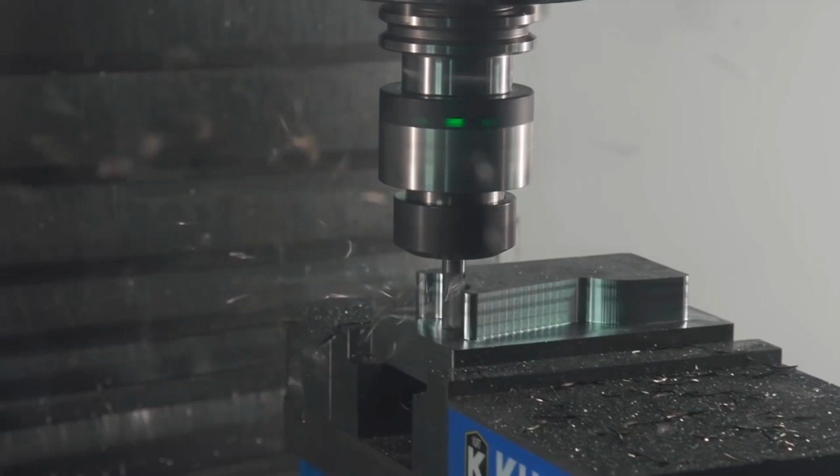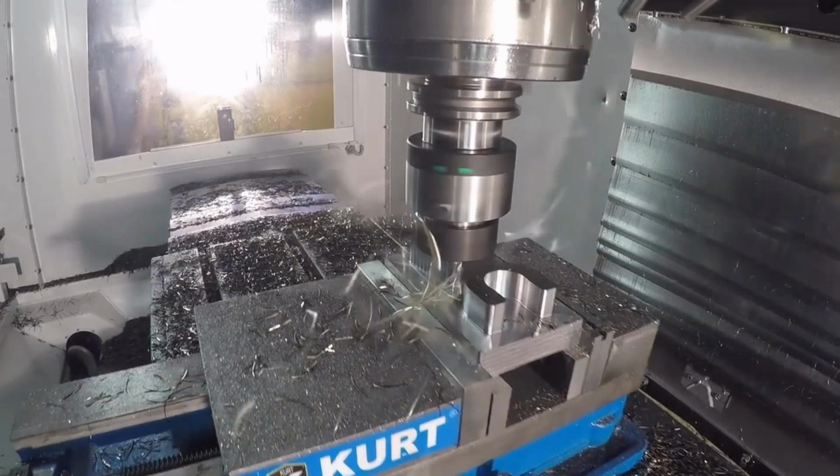If we look at some of the full 5-axis functionality itself, we've got swath cutting, multi-axis contour, so for your complex contours, automatic tilting, to use with short tools. Of course, using larger tools, you might promote a crash, so that's a little tip on that. And you've also got the 4th axis tool wrap, which is very nice. If you do a spiral along the cylinder, you'd use that strategy to achieve that.